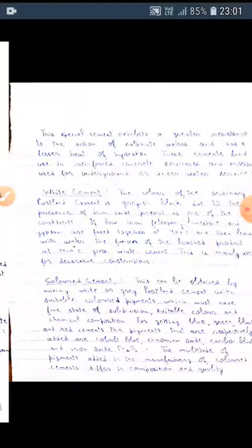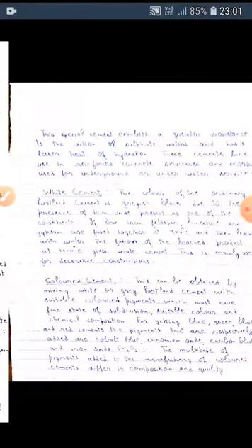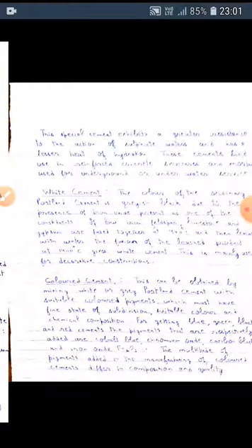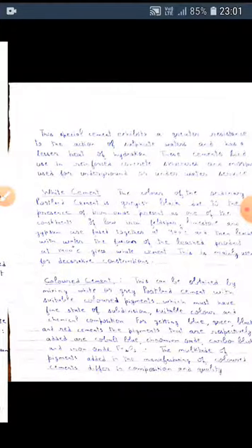White cements and white cement based colored cements of light hues are produced from a clinker burned from a raw mix containing a minimum amount of iron oxides. There should be minimum content of the mineral C4AF, tetracalcium aluminoferrite, in the clinker. The whiteness of the concrete is predetermined by its belite, that is C2S constituent, which impairs cement quality.